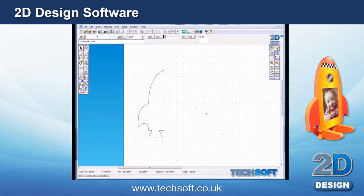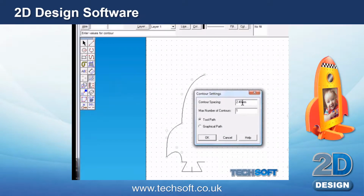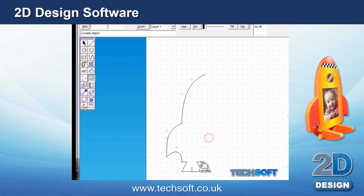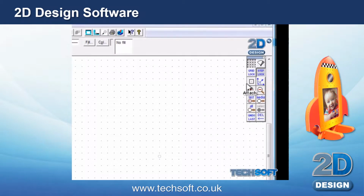We now need to make a slot for the photo frame to sit in. You're going to select the single line tool, draw from the lower construction point up by 1 centimeter, and then use the contour tool. We'll set this to 2.4. OK that, and you'll need to click either side of the line. This now made the correct spacing.